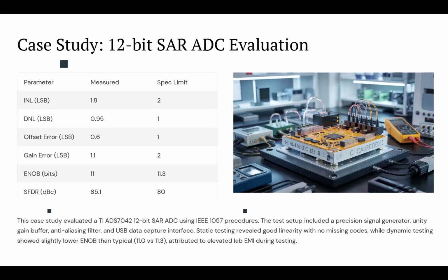So you need to have a metal shield to shield your system from external electromagnetic interference. And you need to verify that your voltage reference is accurate, and you have to use a very high precision multimeter.